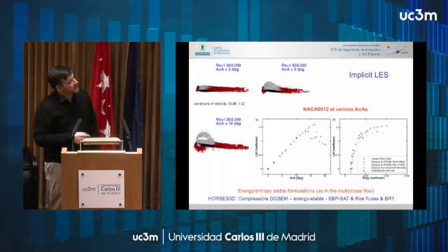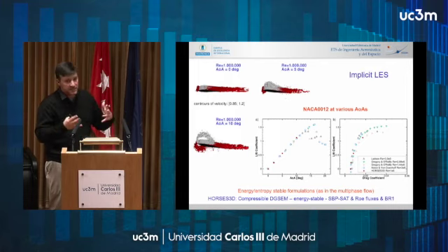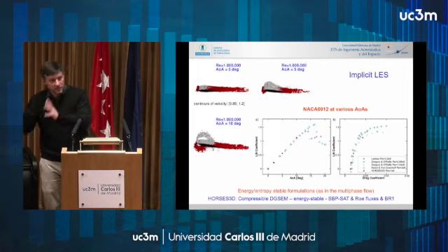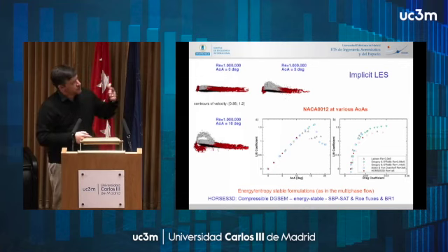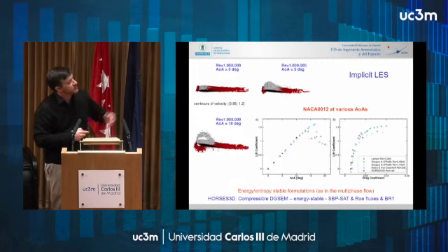We also run LES simulations. And what we see, for example, when we combine these ideas of entropy stability that we saw for multi-phase, we combine it for LES, so same ideas, make sure that everything fulfills the discrete version of the energy equation, such that it doesn't blow up. What we see is very good agreement in terms of lift and drag for these airfoils. For example, that's Reynolds 1 million.